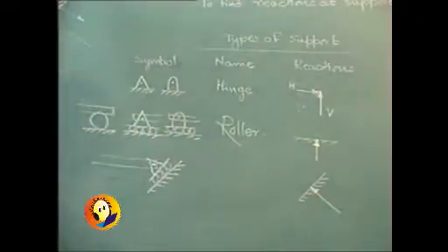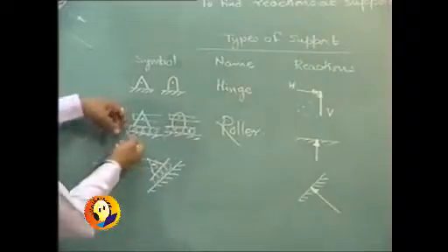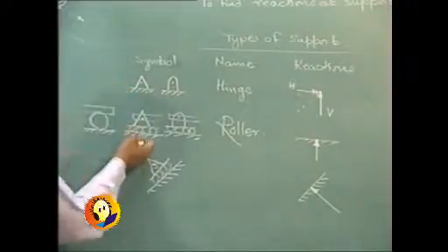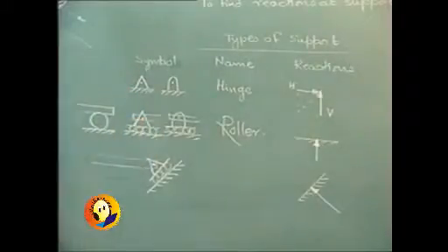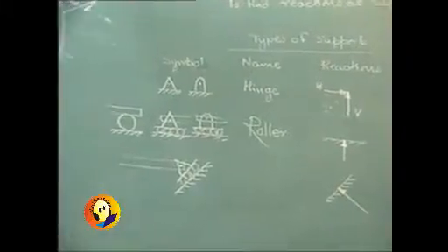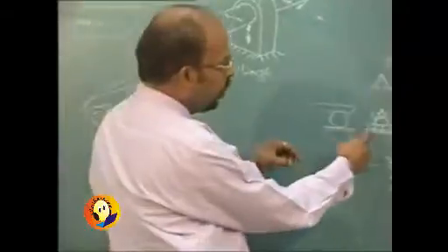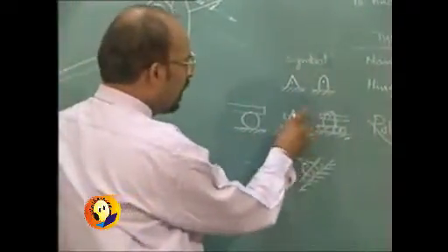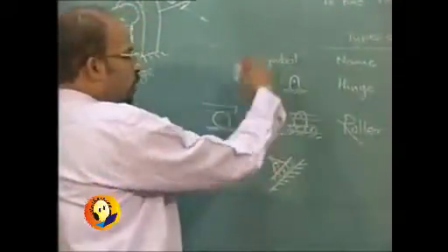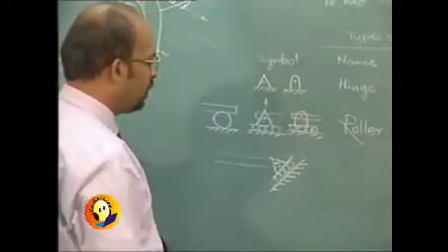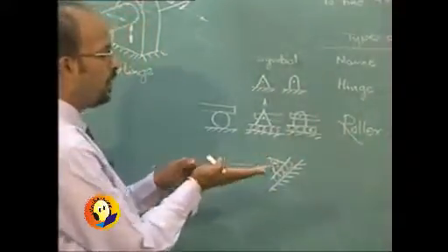And remember that this is simply the roller, there is no perfect contact as in case of hinge. It is not simply resting on it. In case of hinge, it is even locked. In case of rollers, it is not locked. So if I try to pull this up, then these rollers are likely to get lifted. They are simply resting on the particular surface.